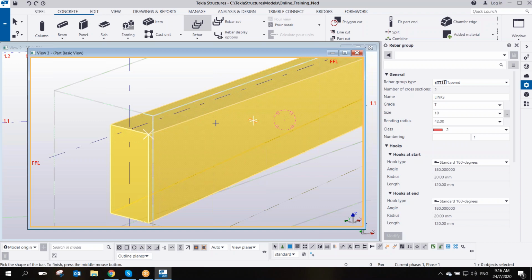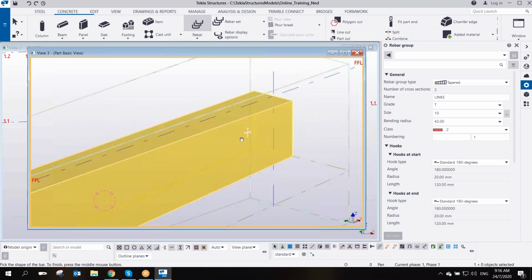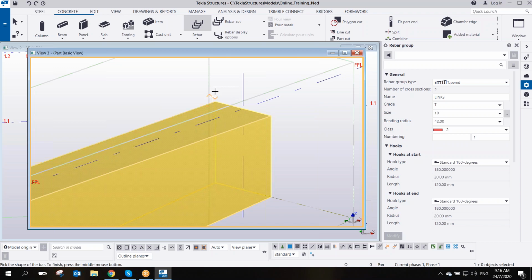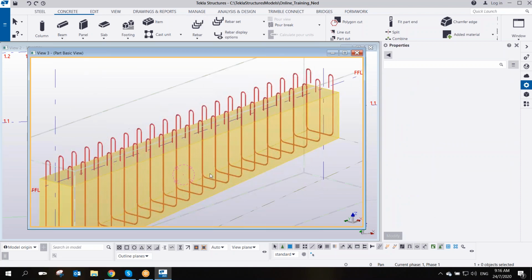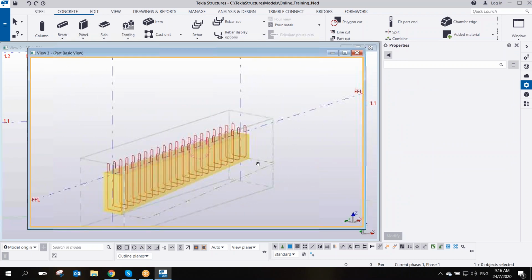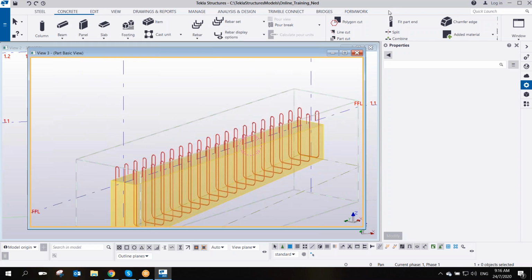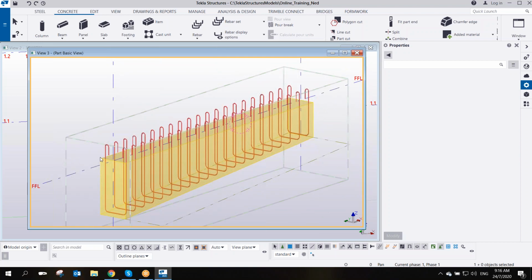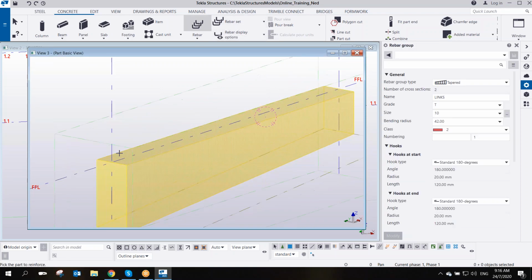Usually we pick the range, but this time I'm going to pick the shape again to the other side. I'm going to start again where I started, the side where I started from the beginning. I'm going to click here 1, 2, 3, 4, and then middle button of your mouse. Then you now have the tapered reinforcement. Make sure that you pick the same first pick point on this side to the other side. Why? Because if not, look what will happen if I pick this one.